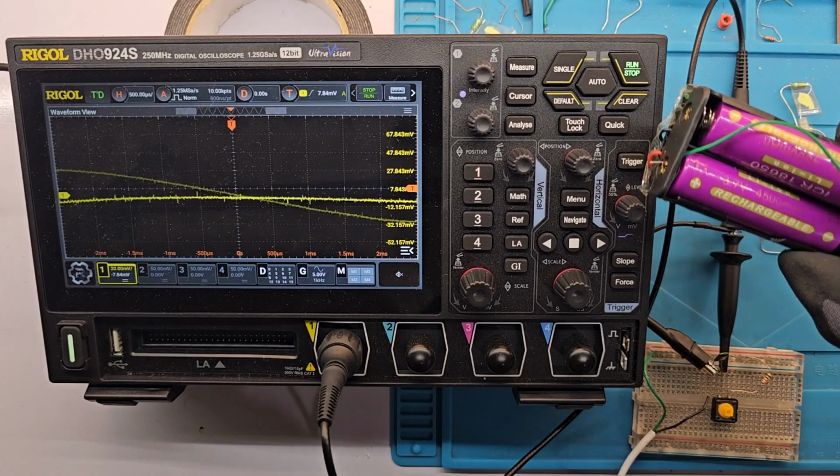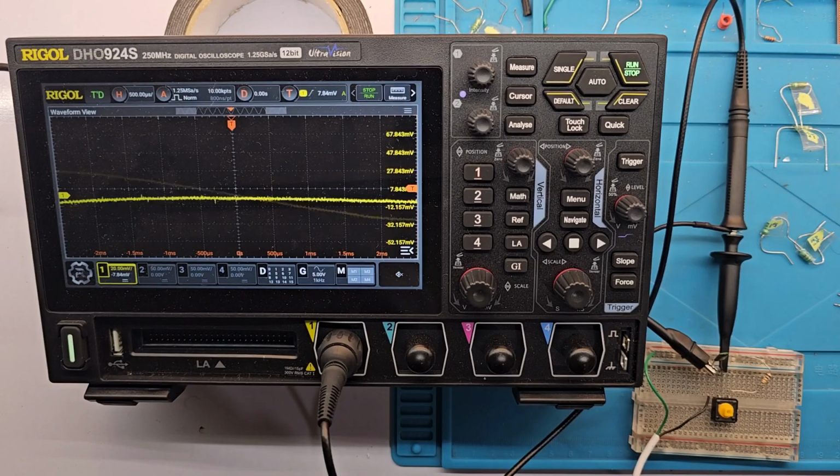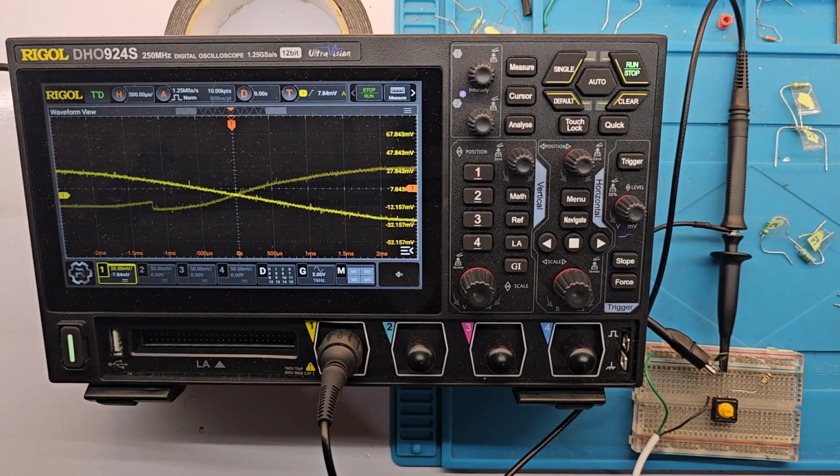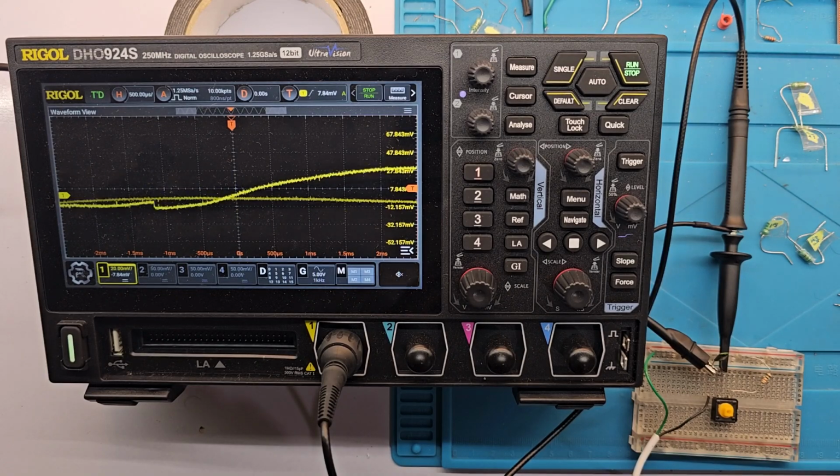The power supply must be as clean as possible. You may run into trouble if you have a switch mode power supply, because they generate lots of noise signals, especially when you're dealing with lower voltages and higher frequencies. The oscilloscope will obviously capture the noise signals coming from the switch mode power supply. So it's very important that your power supply signal is clean and DC.